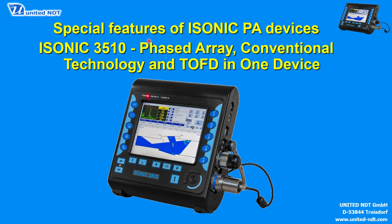Let's look at the instrument from Sonotron, the Isonic 3510. It's a device which has everything on board: phased array, conventional technology, 2 channels, and TOFD, 2 channels, all in one device. And one can already see here on the screen, you not only see the settings of the instrument, you also see an image on the screen which shows you the part under inspection.